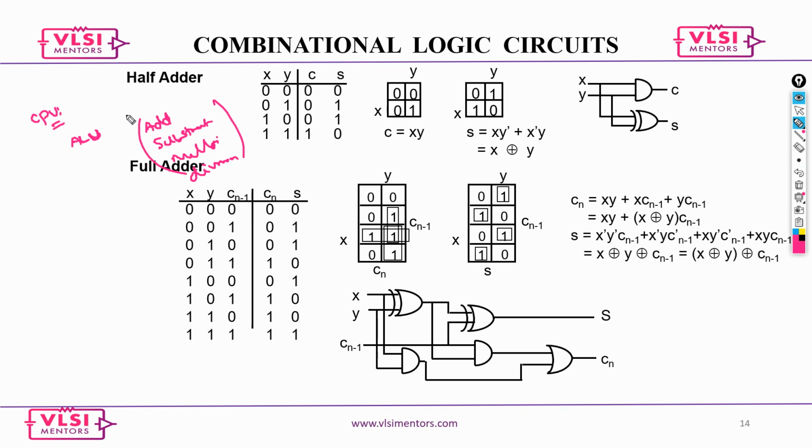So basically the adders are one of the basic building blocks for any designs, and they would be used a number of times. If you look at adders itself you have different types of adders. Say for example, if you need an efficient adder that is hitting high frequencies, you might pick a different type of adder, and then let's say you are looking at area, now you might pick a different type of adder. So that's why we say when you are doing optimization, you should set the settings where the tool would pick the right thing that it has to do. Okay, so let's talk about the basic adders.